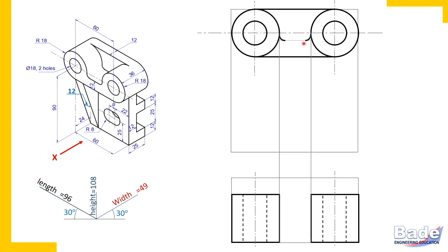To draw such smaller curves, you may use a circle template. So draw those curved edges and then the portion of the edge which appears as a horizontal edge you should make dark. So this is how we have completed this particular edge, which is 12 mm from the lower tangent to the two circles. Now, yet it is not complete. When this plate is connected to the cylinder, check the joint, that is this line, and here this curved line. Here, this ring-like front surface of the cylinder and this strip-like surface are in one single plane. So these two lines should disappear here.